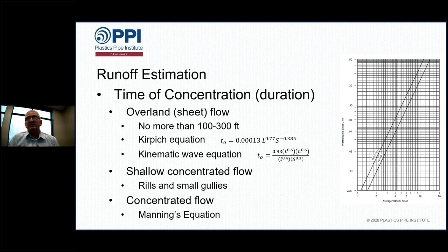Then when you actually get into concentrated flow, that's like a river or a stream or a larger gully, and for that, you just use Manning's equation. You add up those 3 times, and that's how you get your time of concentration.